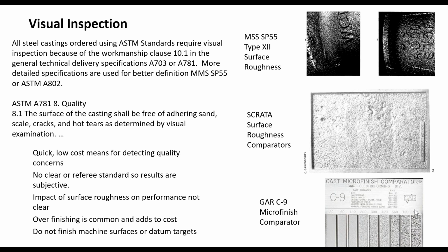These were intended to be RMS, but we've done measurements now, and these numbers aren't really very meaningful in terms of characterizing those surfaces. And because of the uncertainty here, we're actually working with Iowa State University and Frank Peters to try and come up with a white light or a laser scan method of quantifying the surface finish and quantifying those irregularities like pores or scabs, so that we could have a numerical standard, because without a clear referee standard, I don't know how to comply.